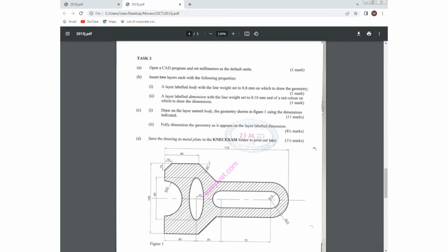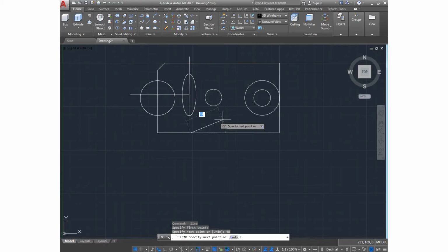What was the angle? At an angle of 45 degrees. So you can see there are two points here, one showing the angle, the other showing the distance of the line. So set the line in such a way that it is on a 45 degrees angle. You can move the line forward to see the angle. There, that's 45 degrees.